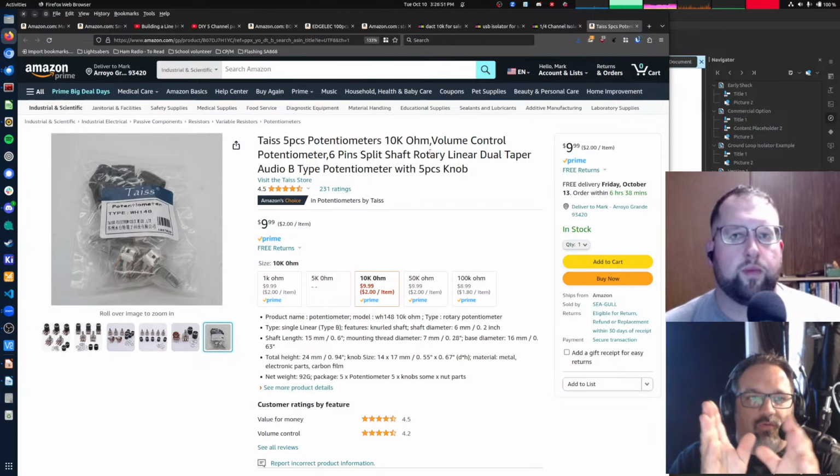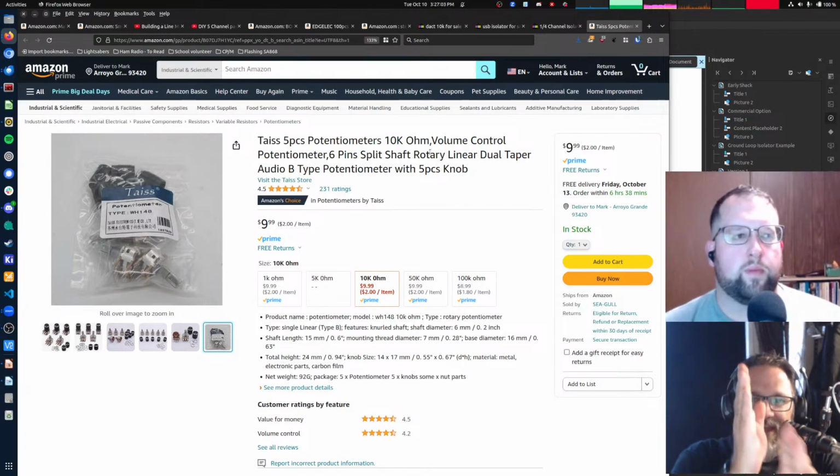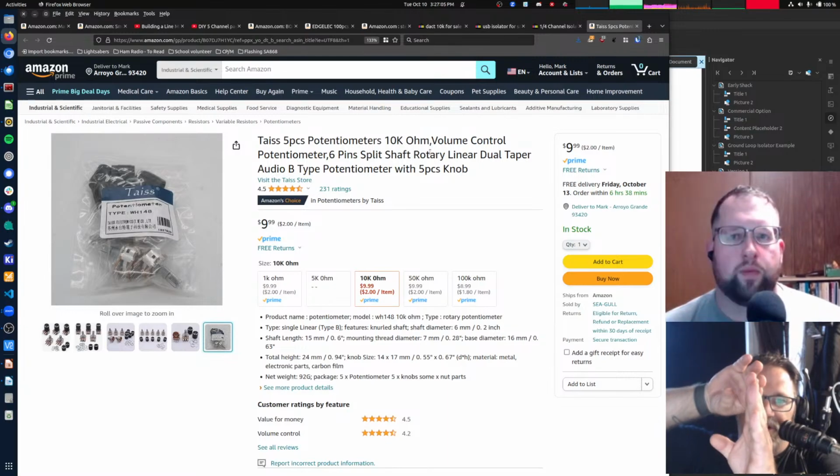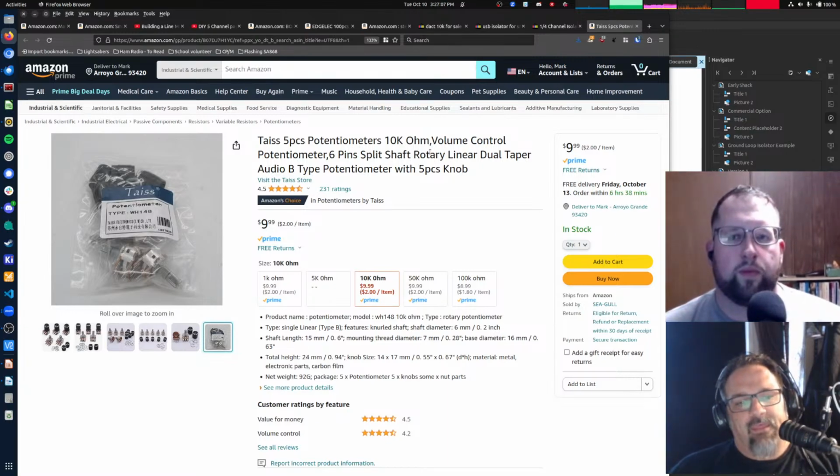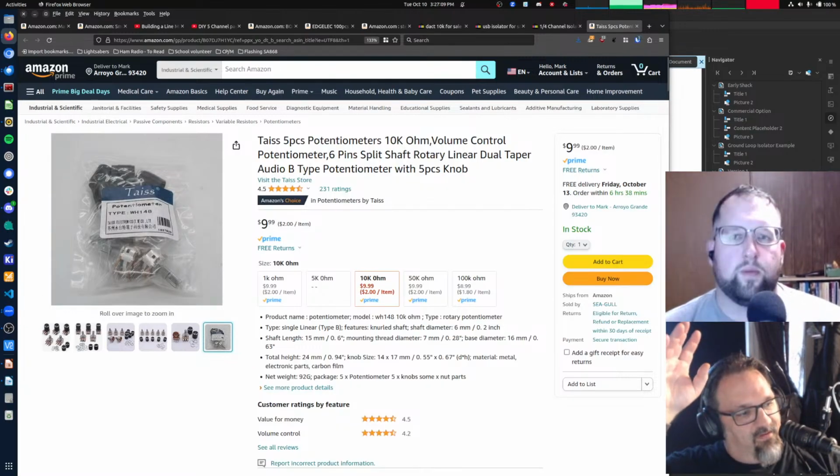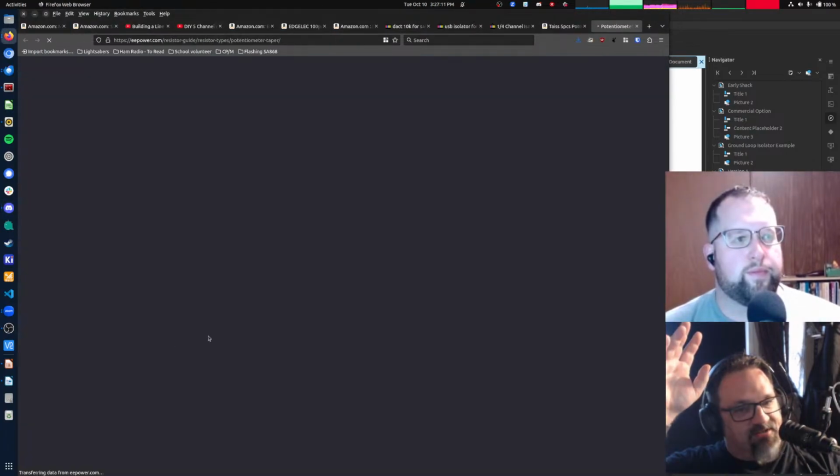And so you want to have more control at the low end of your volume knob. That's why it does 0 to 10% over half of the swipe, and then from 10% to 90% over the second half of the swipe. Anyway, audio tapers versus logarithmic tapers.